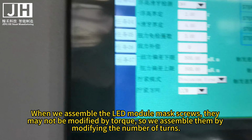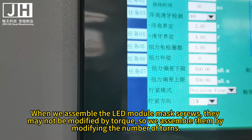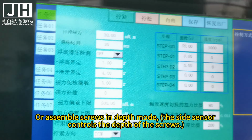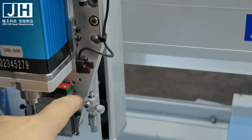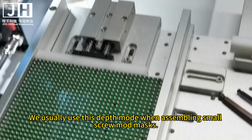When we assemble the LED module mask screws, they may not be controlled by torque, so we assemble them by modifying the number of turns. Or assemble screws in depth mode. The side sensor controls the depth of the screws. We usually use this depth mode when assembling small screw module masks.